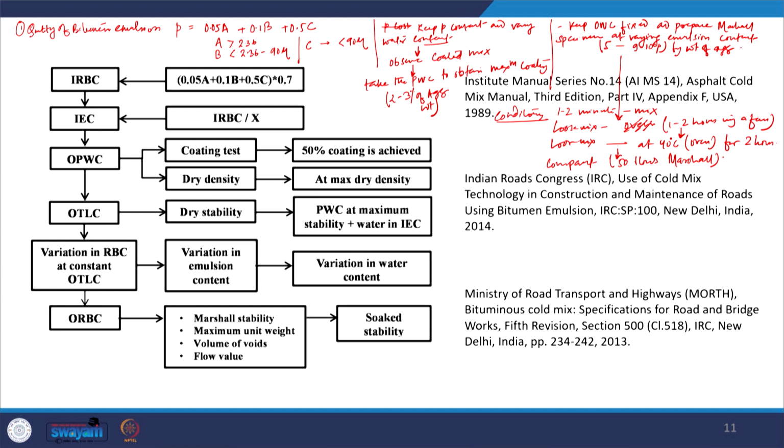All right. Then you extract the sample. Then again the compacted specimen you have to condition in oven. Extract the sample after 24 hours. Then you condition the sample at 40 degrees Celsius in the oven for 72 hours. So, you can see the curing process is different, and it is a tedious process here. In fact, in any cold mix asphalt design, you have to subject it to long period of curing, and then you have to perform stability test at 25 degrees Celsius. Some specifications also require carrying out indirect tensile strength test on the compacted cold mix asphalt specimen to complete the mix design process.